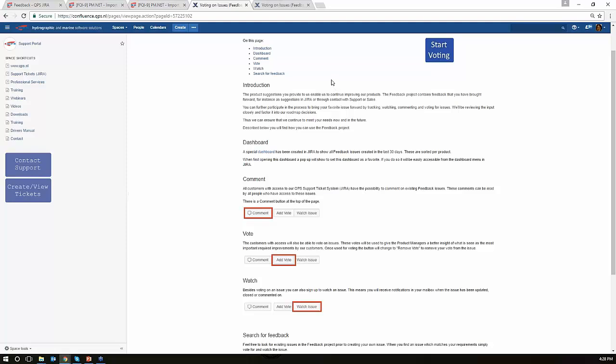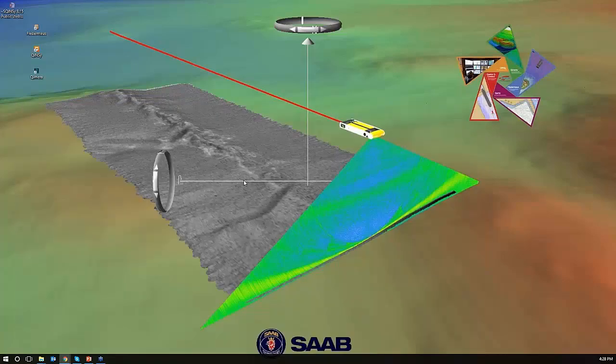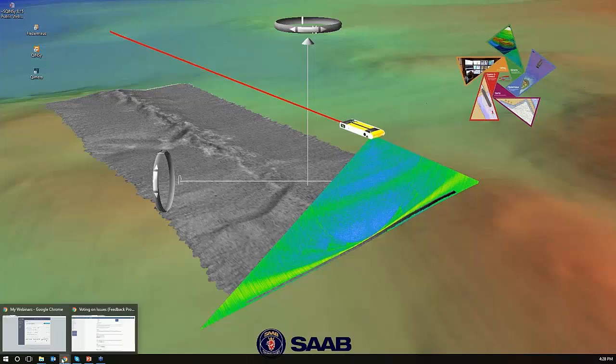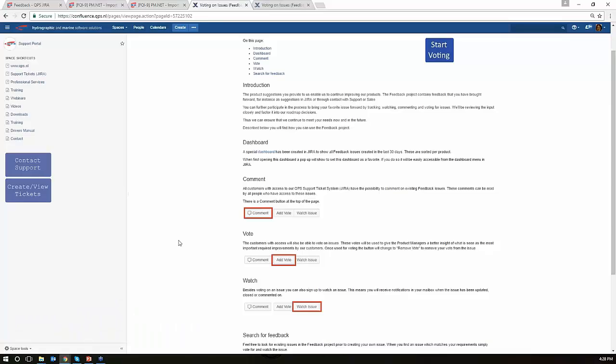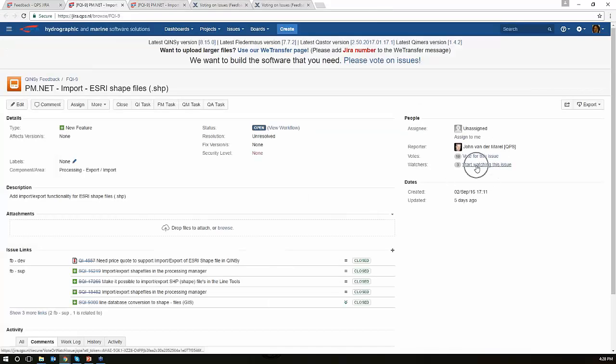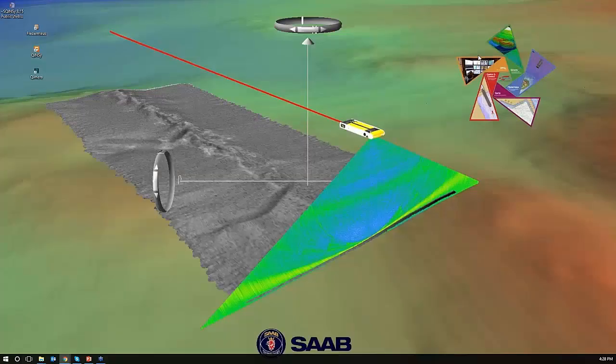Okay, thank you, Evelyn. We have a couple more questions coming in. Again, a question about the process manager. John, a question is here. When erasing from the sounding grid in the process manager, does the erase tool erase data on multiple layers of the grid, or can you select the layer that you want to delete on? The erase in the processing manager that you execute on the sounding grid file is per layer, or there's an erase option for all the layers. But in principle, it works on a single layer.